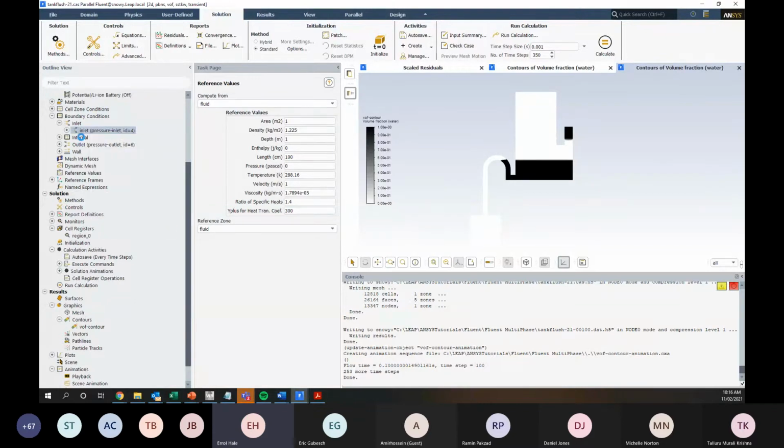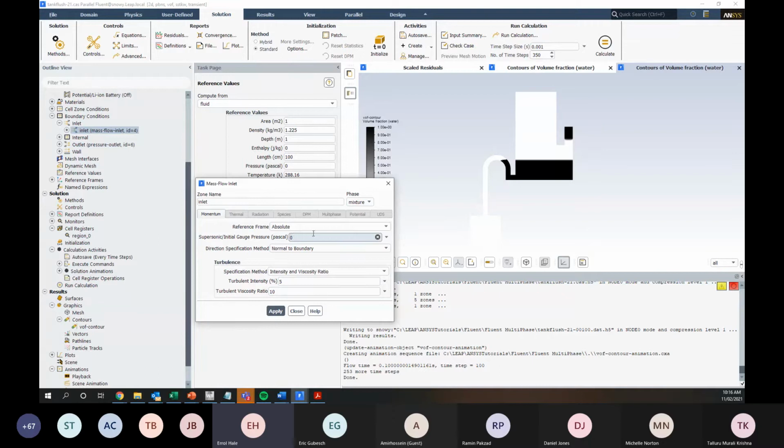It's very similar to your pressure inlet or your velocity inlet, where you specify exactly how much is coming in, which in this case you have to specify through the mixture, through the phase. But then the other thing is the turbulence specification. So very similar. So it's just gonna calculate how much fluid or gas is coming into the domain, and then what the turbulent quantities of that fluid are.